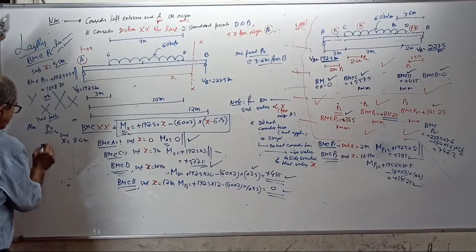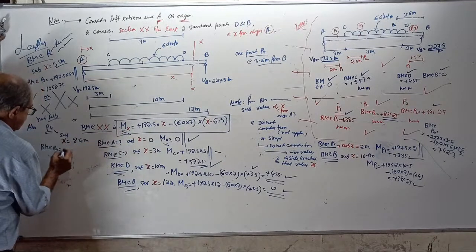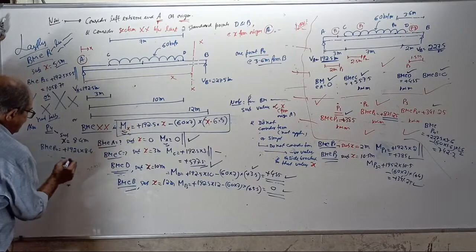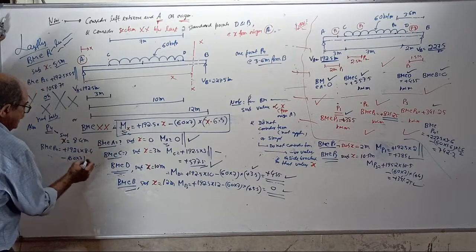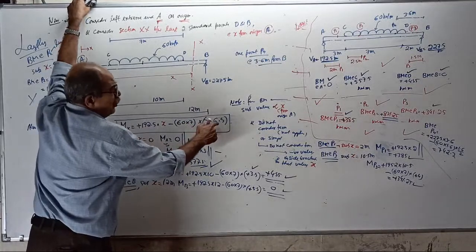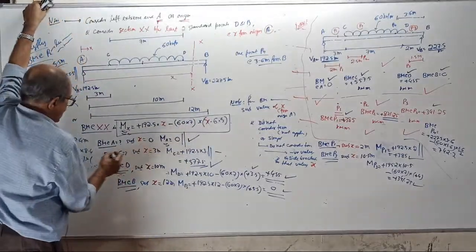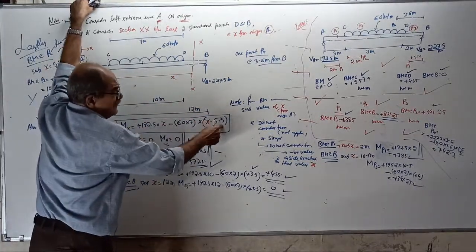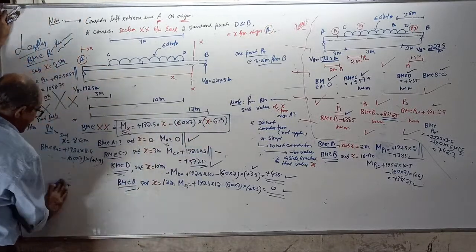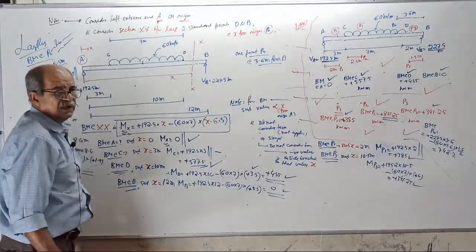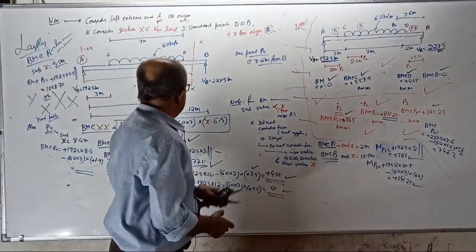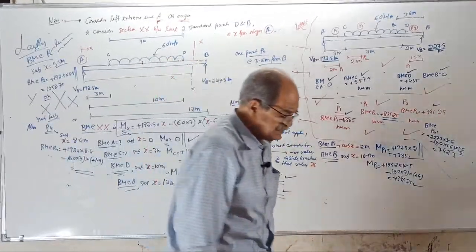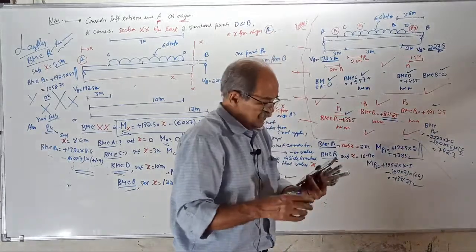Then bending moment at P4 equal to plus 192.5 into 8.4 minus 60 into 7, that is the total, into 8.4 minus 6.5. Plus 1.9. See, when you put 8.4 here, this is positive, therefore it is to be considered. Why? When x minus 6.5 is there, it is considered for any value of x more than 6.5. Answer. Over. Today's last answer from you.